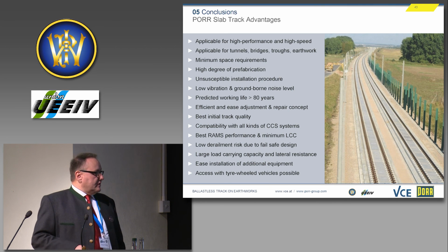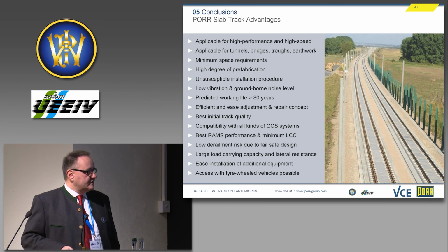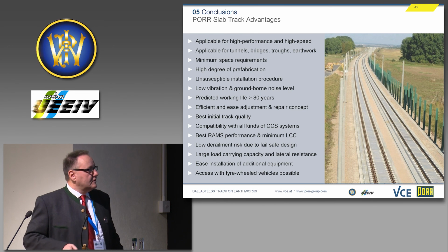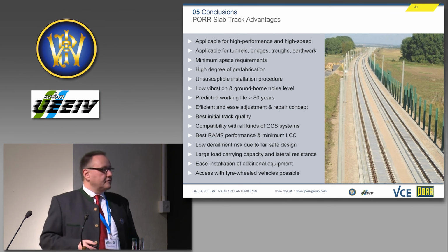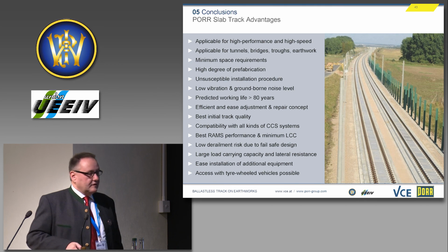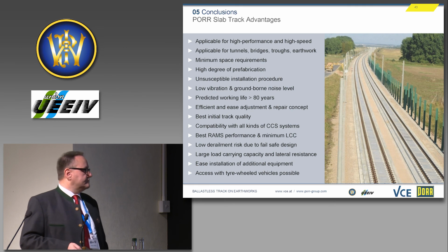We have a large load carrying capacity and a large lateral resistance. We did some tests in Germany where we applied horizontal forces with jacks on a single slab. We removed the rails and put forces on the single slab, and it was not possible to move the single slab up to loads of, I think, 1,000 kilonewton for one slab, which is much more than needed.